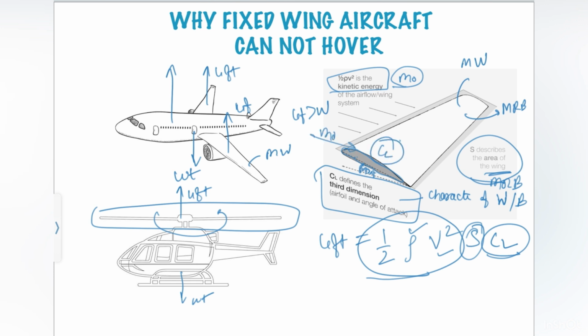If we go further in depth, there are charts and graphs which give you the value of the coefficient of lift as per the angle of attack, and that's how you calculate the lift. So you have the coefficient of lift, which is the characteristic of the wing or the blade, the surface area, the relative velocity of the mass of air and the surface, density and the constant.